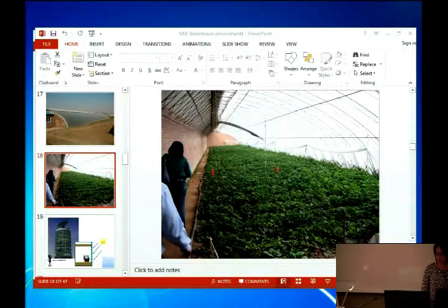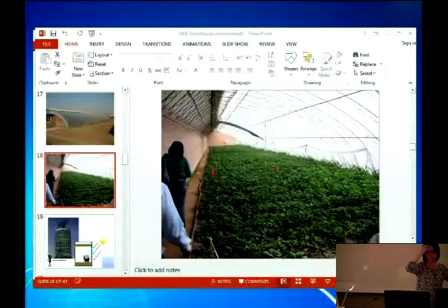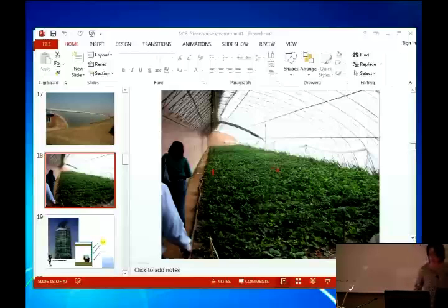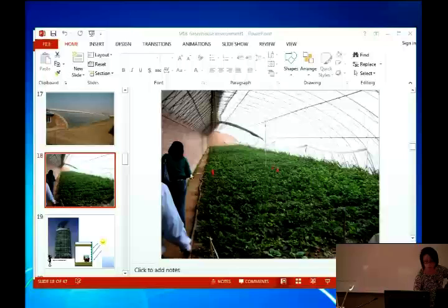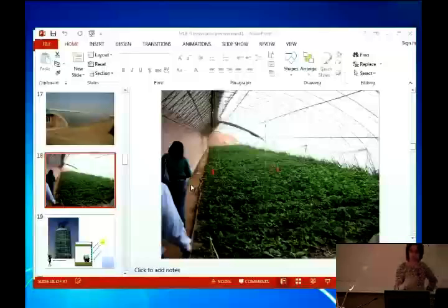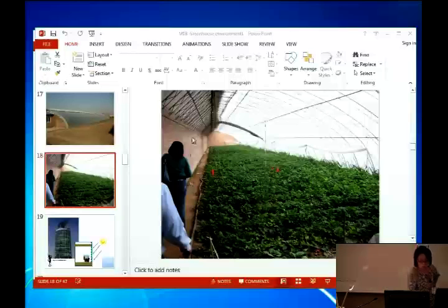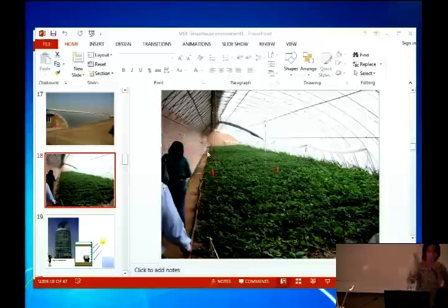All right. So Monday we started talking about greenhouse environments, and this is the week of greenhouse environment. And one of the students asked a question. This is a Chinese greenhouse, and the purpose of a Chinese greenhouse is absorbing radiation in this north wall, so that it can be the heat sink, and then it can be the source of the heat during the cold winter night. So to increase the radiation, how about putting a mirror on that wall, which is a great question